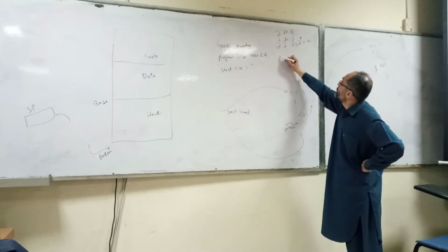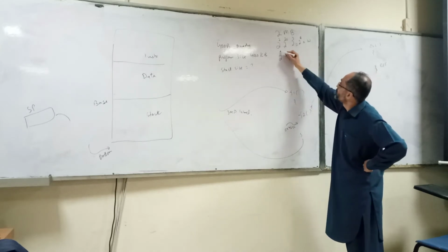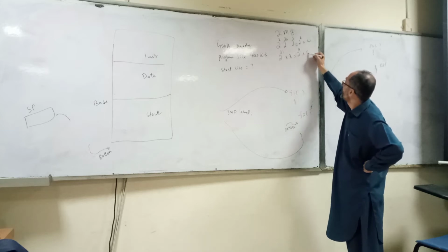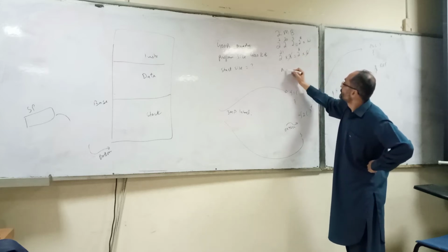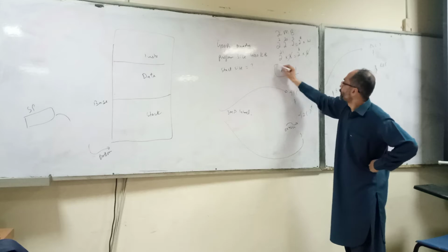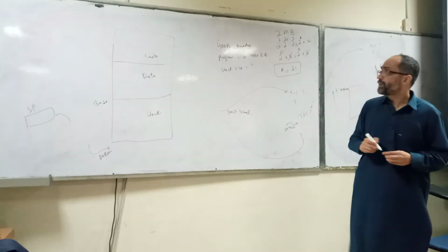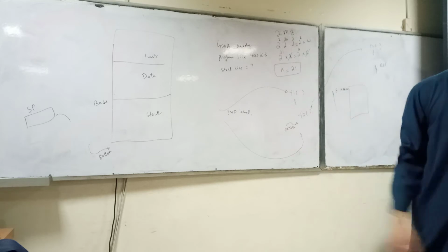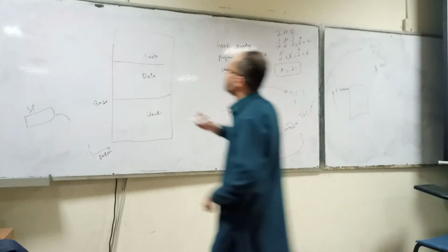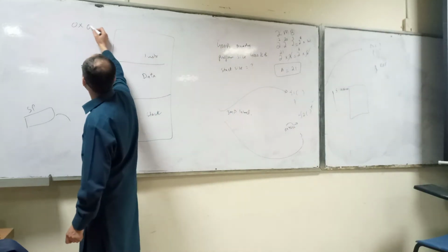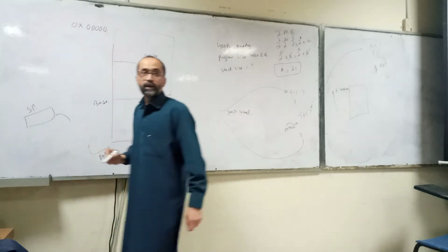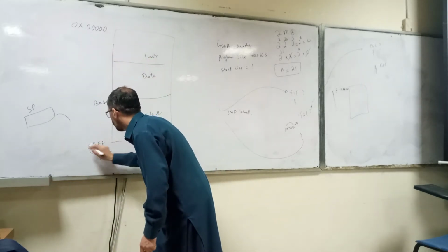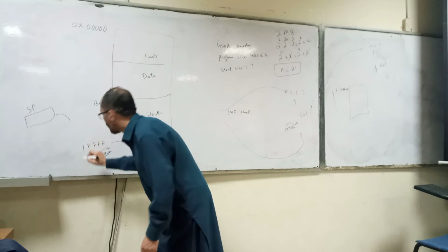Let's assume W is 8. So it is 2^21 × 8, which is 2^A × 8. What is the number of address lines? 21. What is the minimum address and what is the maximum address? The minimum address is 0x00000, and the last address is 0x1FFFFF. Why 1?